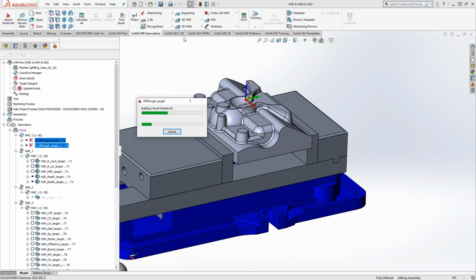So in that stock and target comparison, if you remember mine, it was set to 4/10 and then 4 thou on the negative side. But we are measuring with facets that are 50 thou. There's no way we're going to get something as detailed as 4/10 if we're measuring it with building blocks that are 50 thou in size. So that red and orange color could simply be that the facet has been flipped 180, because that's literally what those facets are. They're either in one direction or another. So you always have to remember that your facets need to be as tight as, or tighter than, your target and machine stock comparison.